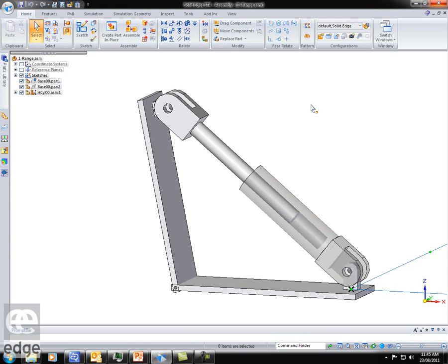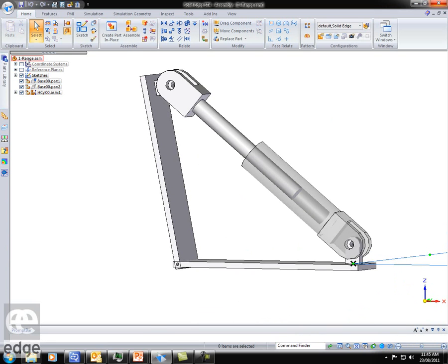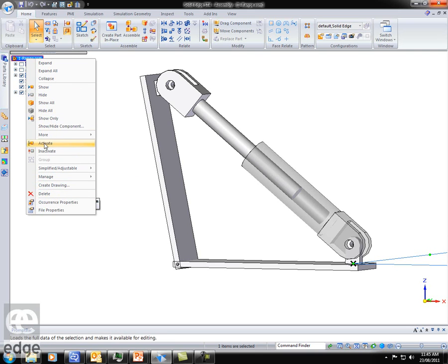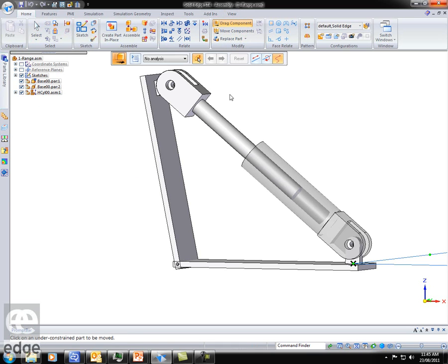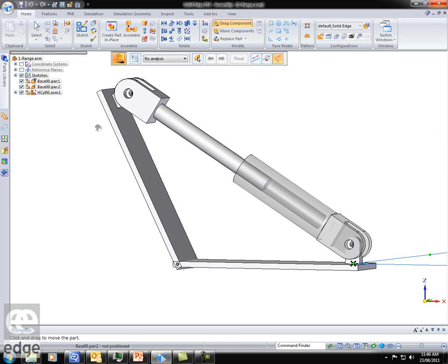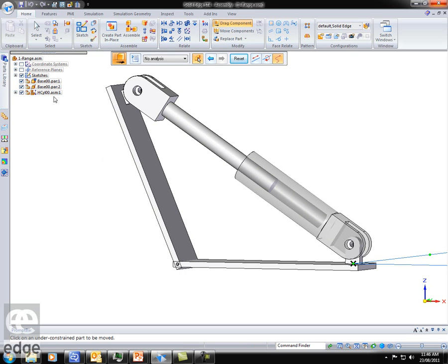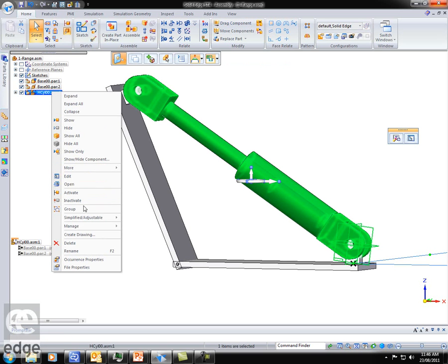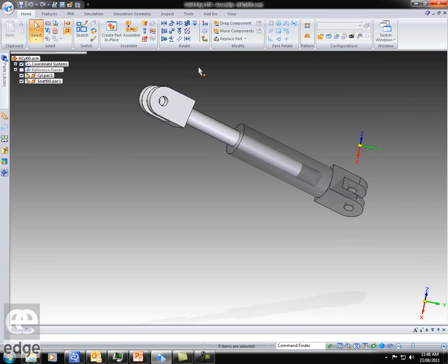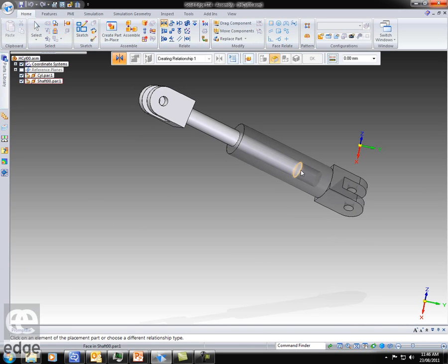One of the other changes to assembly has been in this area. This is one that has been frustrating, I know, for a number of us for some time. If we do an animation of a component like this, the subassembly in it, and I pick that, we've had no constraint over distance, so those sorts of things can happen. Well, let's see what we can do about that. Let's edit that cylinder. I'm going to use a mate relationship from that face, and I want to set a new distance. We had fixed and float before. Now we've got range. I'm going to make that 4 millimeters to 240, I think it is. That should do. And the other end of the mate is to there.